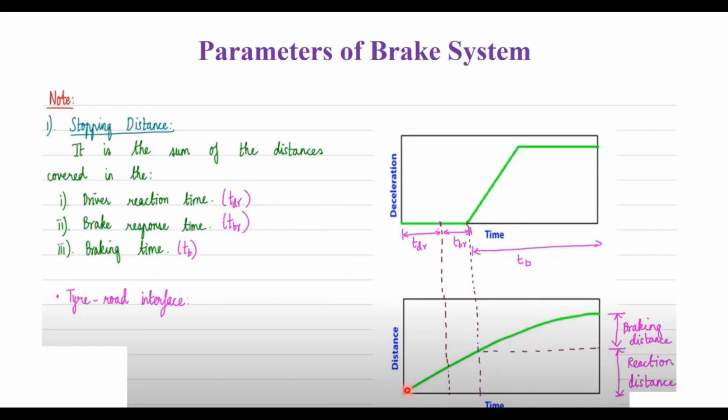And also this reaction time or the braking time, it also depends on the tire road interface. See what happens, reaction time may be same, brake response time also may be same, but the braking time, if the road is wet because of the rain, it also depends on tire road interface.